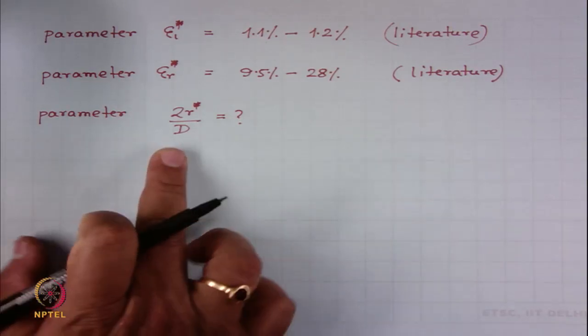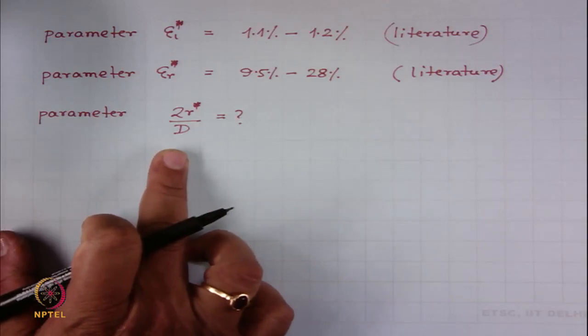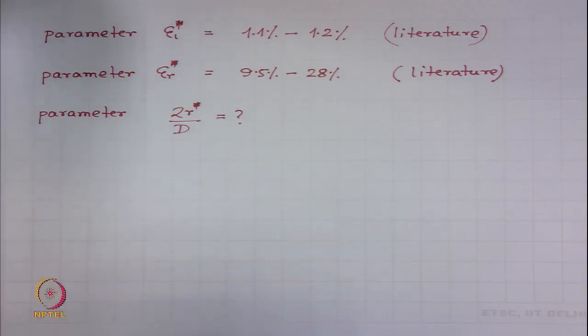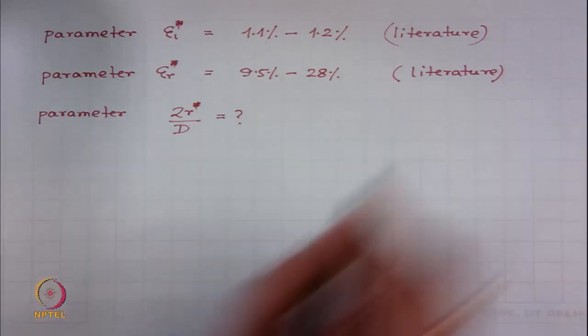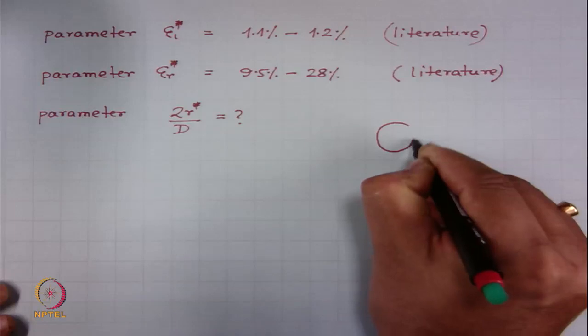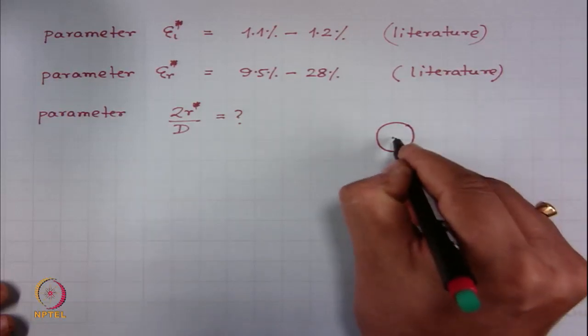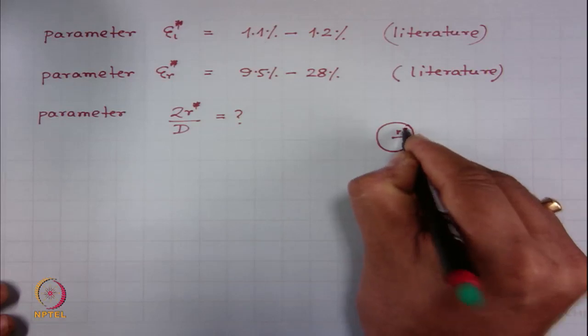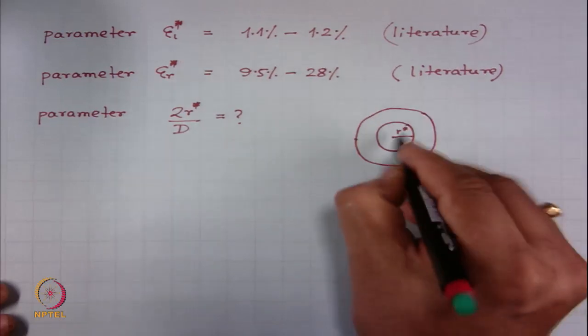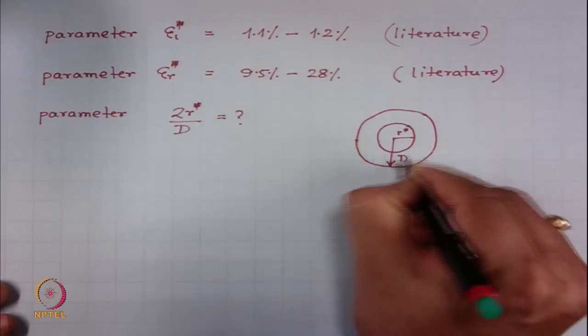This is the relative position of the neutral fiber inside the yarn. Based on helical model, constant value of packing density at each radii, we can estimate this position by dividing the area into two halves. That means the radius is r star and this is the yarn whose radius is d.